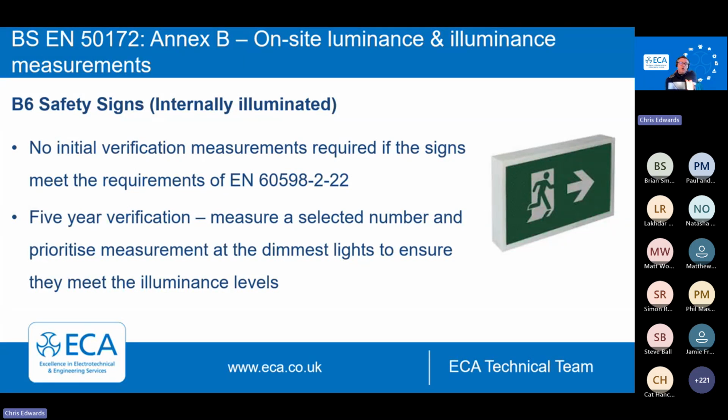When it comes to initial verification and your measurements, if you have similar areas, say for instance you've got an office block and floor 36 is exactly the same layout as floor 37, exactly the same lighting design, exactly the same fittings, you only need to verify one floor. Okay, coming back, I just thought of that and it was important that I mentioned it.